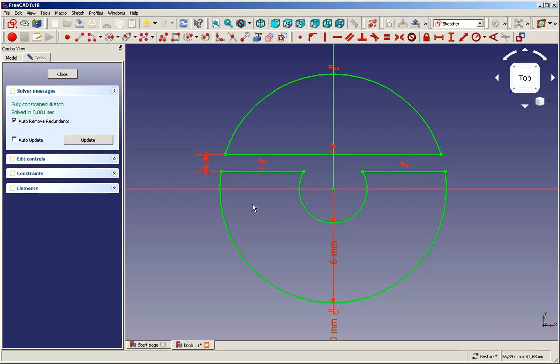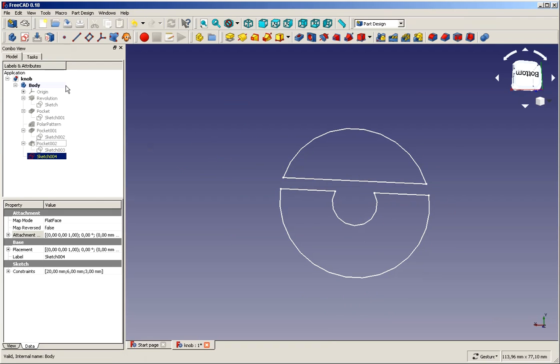define it again. Sometimes if you do such constructions where you do cutting and so, it makes sense not to define your constrained dimensions first, but finalize the shape of the object and then create your constraints with numbers, because you may, as you've seen, take away your reference point.